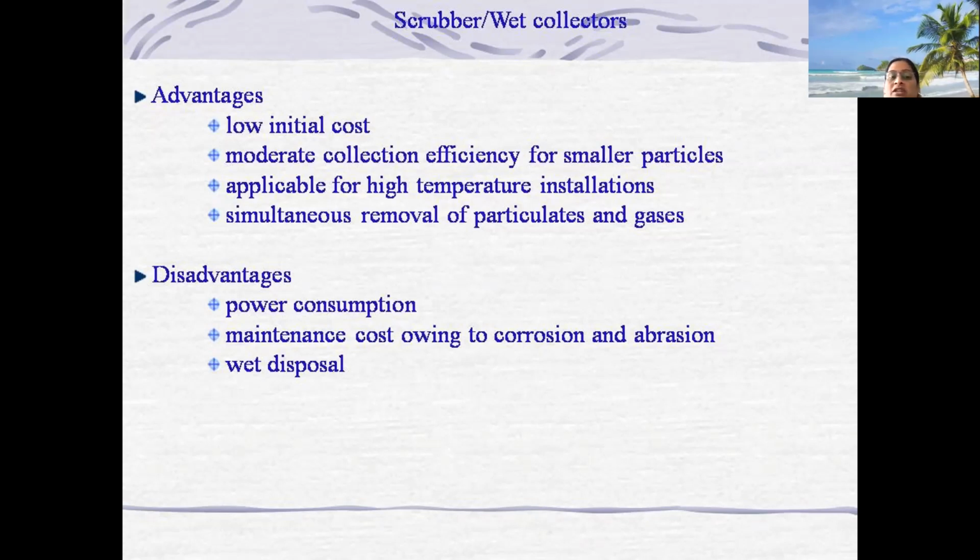Advantages: all these have low initial cost, moderate collection efficiency for smaller particles, are applicable for high temperature installations, and perform simultaneous removal of particulate and gases together. Okay, and what are the disadvantages? Power consumption is very high, because we are suddenly increasing and decreasing the velocity of flow, so there is a power consumption.